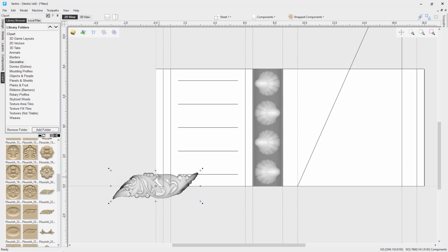So with that in mind, let's hold the Alt key on our keyboard, and left mouse click into the center of this current clipart. I'm going to drag that out and see where the edge lines up with this one in a nice way. Now, if you look in the bottom right where I was hovering my mouse pointer earlier, you can see I've got a value of 4.5825. We can round that up to, sorry, to 4.6. So I think 4.6 is going to be the value I'm using here because it gives a very tiny gap, but nothing where there's anything overlapping too much. So I think that's a pretty good value. So 4.6. Let's note that down somewhere. So I've got 4.6 written down next to me at the moment.